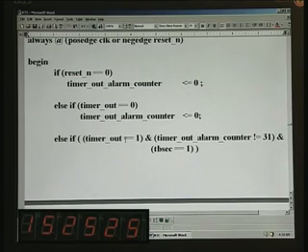This can be high only when the terminal count is reached, isn't it? So, that terminal count is different; this counter is different. This counter is only for sounding the alarm. We need to sound the alarm just for 30 seconds, otherwise you get annoyed with the buzzing sound all the time, right. Whereas timer out is the one when the set time matches with the running time, or stopwatch for that matter, only for stopwatch, matches with the set value in the count mode, be it up or down, then only timer out is set, only after the lapse. After it is set, then only this 30 seconds will come into play.